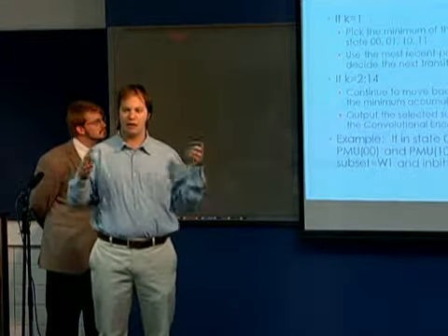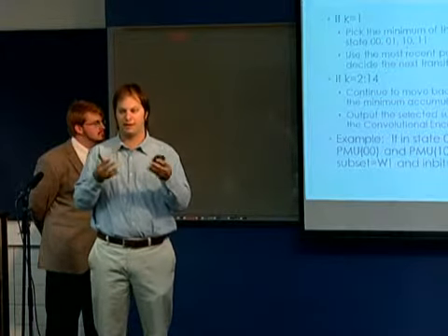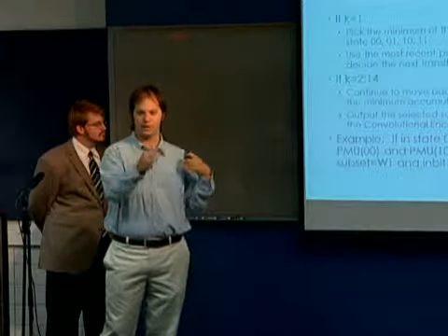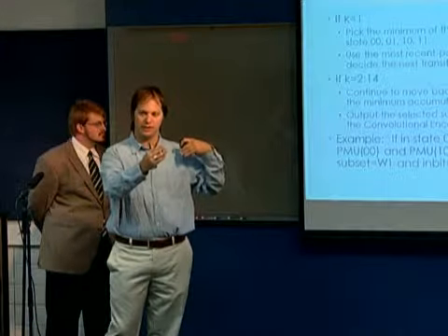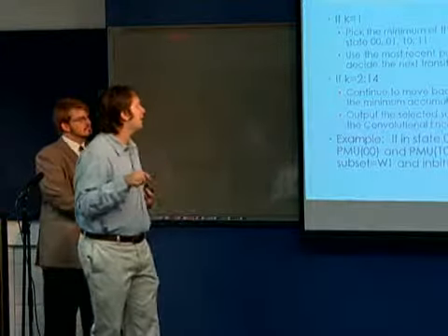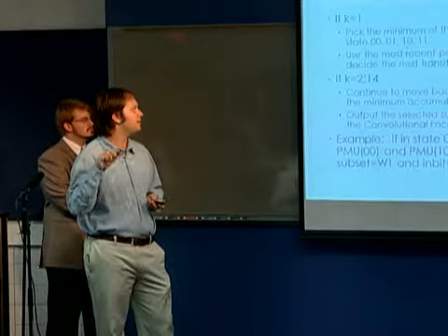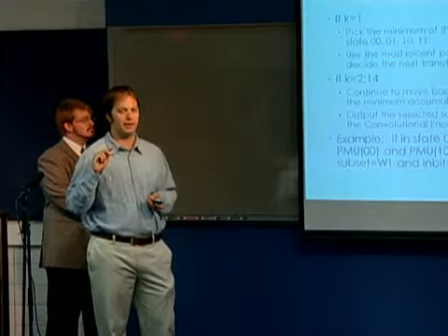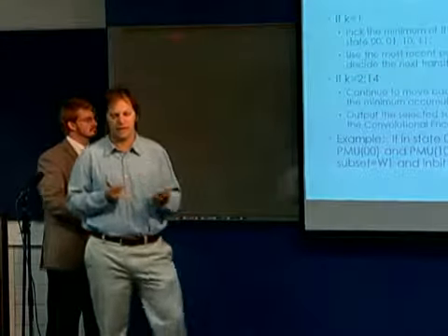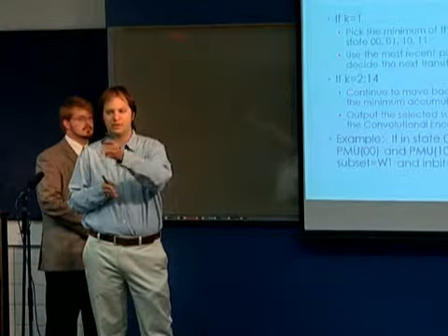So once we have our 14 accumulated path metrics, we start going backwards through them. We take our 14 by 4 matrix and we flip it. If we're looking at the first one, we pick the minimum of the accumulated path metric unit because that has the most information. It has gone through 14 transitions.